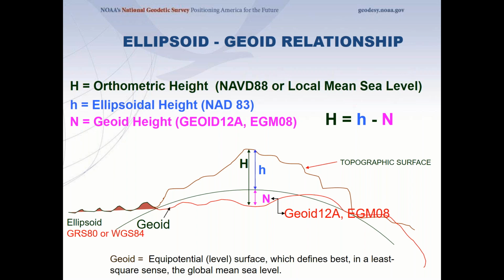Now, this is very important to remember: you have to watch your sign convention. In the United States or CONUS, the geoid height value is a minus. So really, to determine orthometric height, a minus times a minus makes a positive, so you're adding. But in the Pacific, it's just going to be a negative. You're going to take the ellipsoidal height and subtract the geoid height.